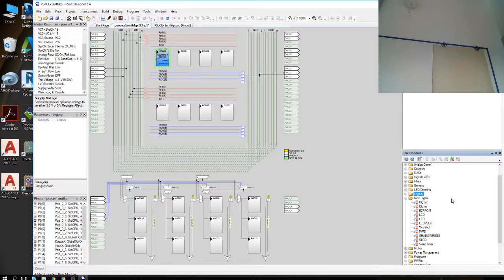7-segment LED. Good. One shot. Pulse width detector. Not just can you do pulse width modulation, but this can also be used as a pulse width detector. For example, with ultrasonic rangefinders, the pulse width being measured gives the range. So you could use the pulse width detector to measure that.